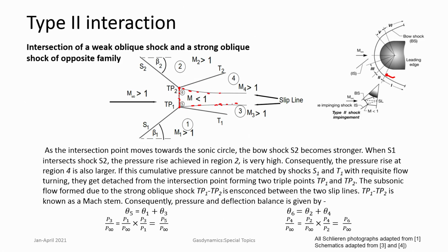So you have two slip lines in between which you have subsonic flow. These slip lines can respond and later they can form even a sort of a shape like a CD nozzle, and this Mach number which is less than 1 can get accelerated further to higher Mach numbers. But here this is a subsonic region which is separate from supersonic regions in 2, 4, similarly 1, 3.